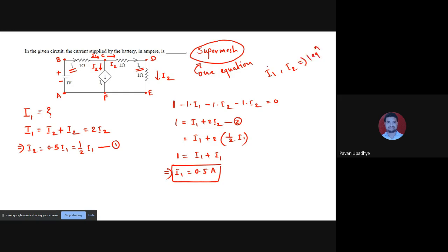So as far as mathematical linear algebra is concerned, you have got a smaller number of equations than the number of variables to be evaluated. So in such a case, the other equation is always given by the common branch. So here in this case also, this is what we could get because of the common branch. So the equation which otherwise could have been got had this not been a super mesh can be achieved by looking carefully at the common branch. Okay.